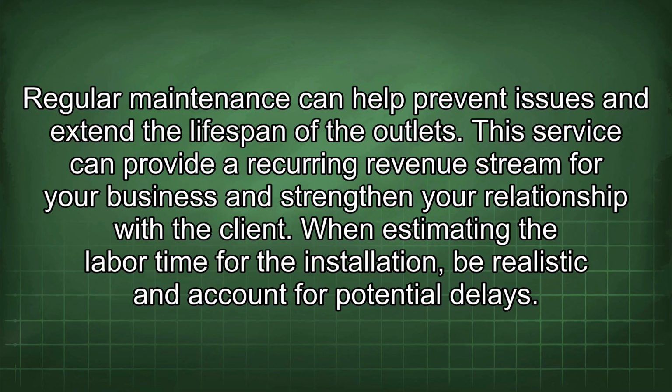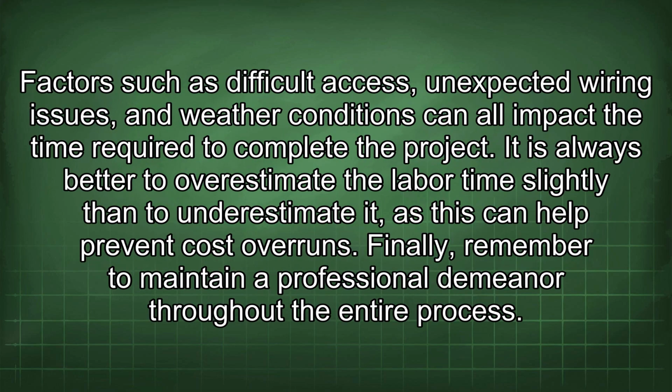When estimating the labor time for the installation, be realistic and account for potential delays. Factors such as difficult access, unexpected wiring issues, and weather conditions can all impact the time required to complete the project. It is always better to overestimate the labor time slightly than to underestimate it, as this can help prevent cost overruns.